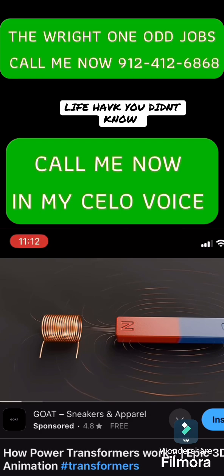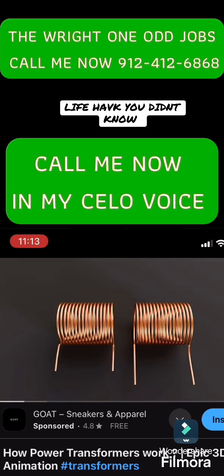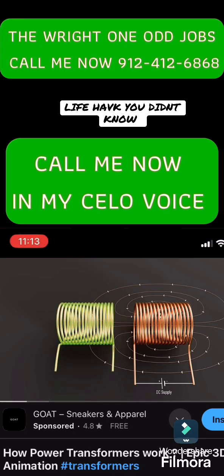A change in magnetic flux is absolutely necessary for electromagnetic induction. If we stop moving the magnet, no matter how strong the magnetic field of the magnet is or how many turns are there in the coil, no voltage is induced in the coil. Let's replace this bar magnet with another coil. If we connect this coil to a DC supply, the magnetic field produced by the coil looks very similar to the magnetic field of the bar magnet. As the magnetic flux linking with the first coil is not changing with time, no voltage is induced in the first coil. That's why electromagnetic induction does not work with a DC supply.